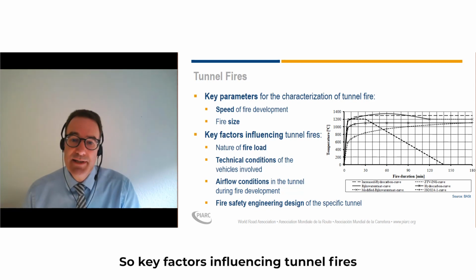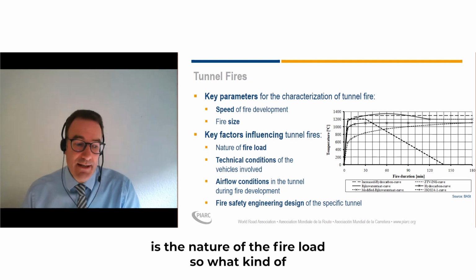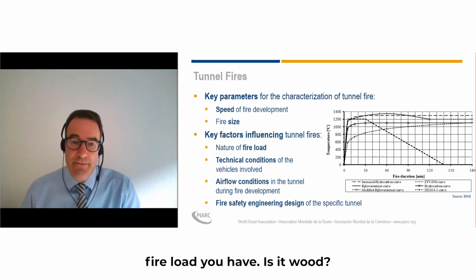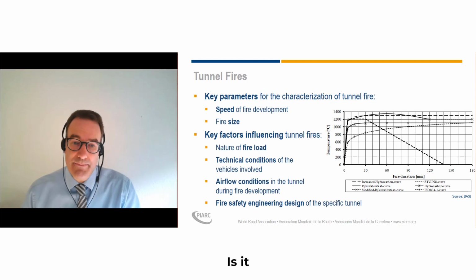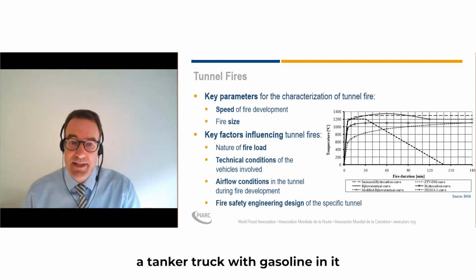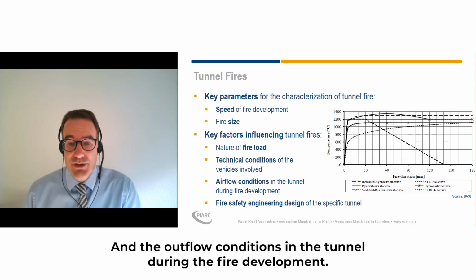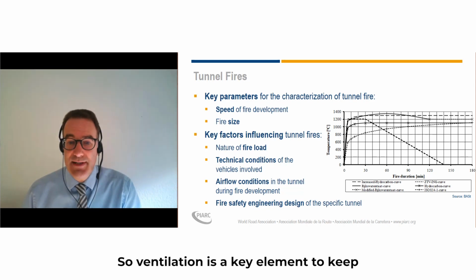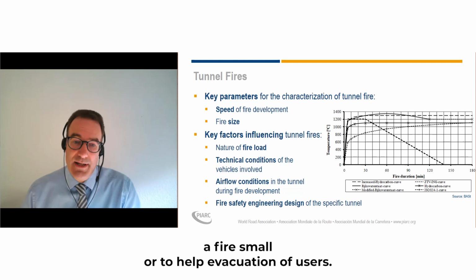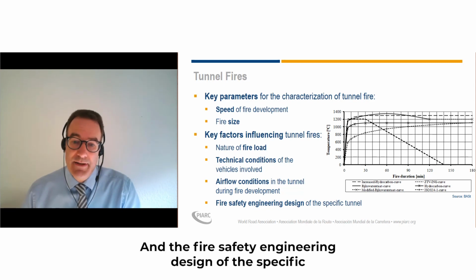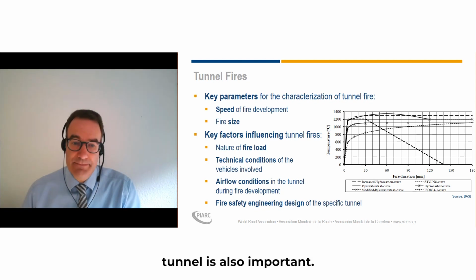So key factors influencing tunnel fires is the nature of the fire load. So what kind of fire load do you have? Is it wood? Is it a tanker truck with gasoline in it? The technical condition of the vehicles involved is very important, and the airflow conditions in the tunnel during the fire development. So ventilation is a key element to keep a fire small or to help evacuation of users. And the fire safety engineering design of the specific tunnel is also important.